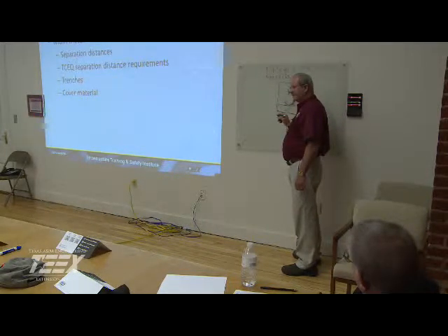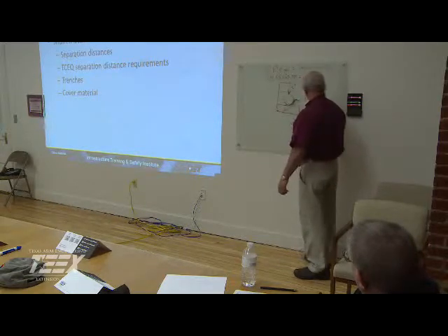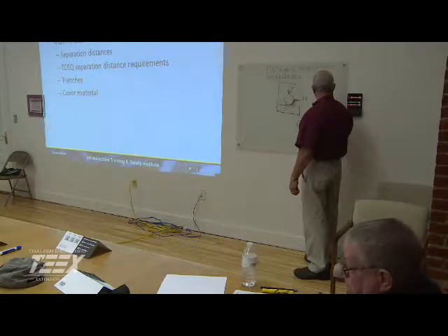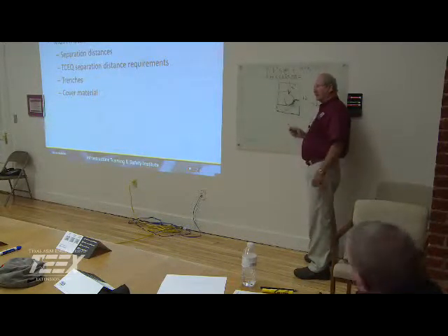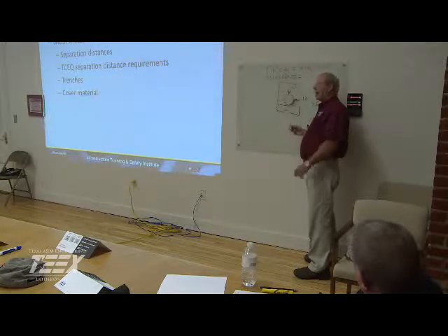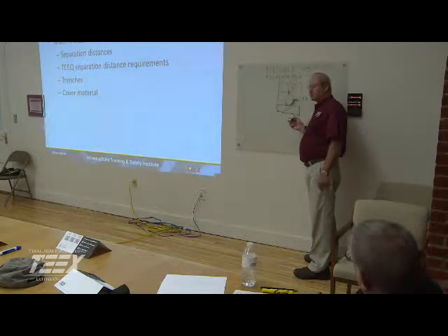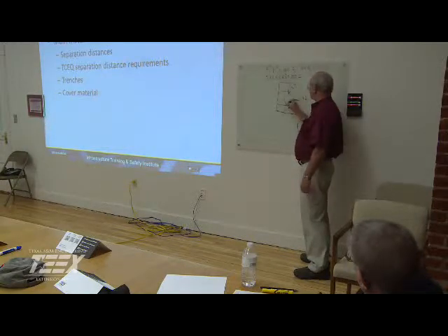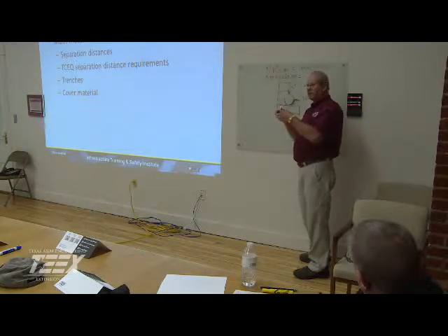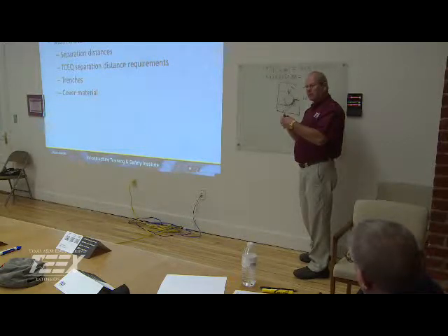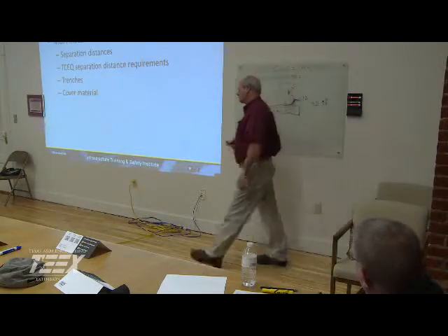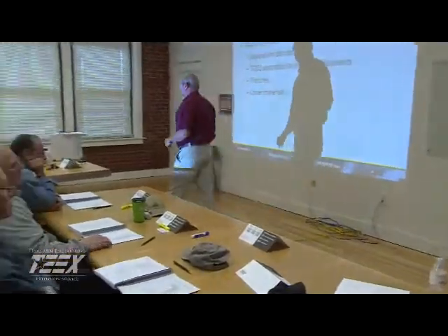Okay? And remember, if you're using ductile iron, the flexibility is about 5% flexibility. That's a tremendous amount of flexibility. I would never do that amount because you're pushing that pipe to the greatest extents. But if you're going to have to flex that pipe, it's better to put flexible joints, you know, the bending joints, to take care of the deflection, because you don't want to have to come back and repair this pipe later. Now, there's 2 different types of corrosion with pipes.